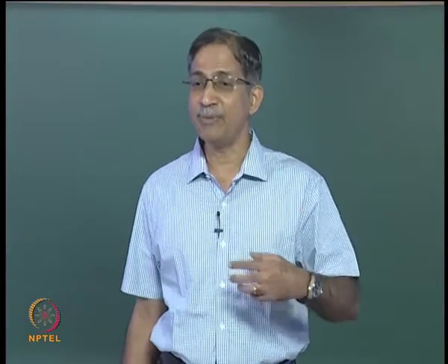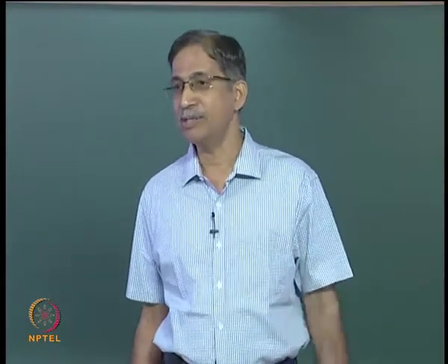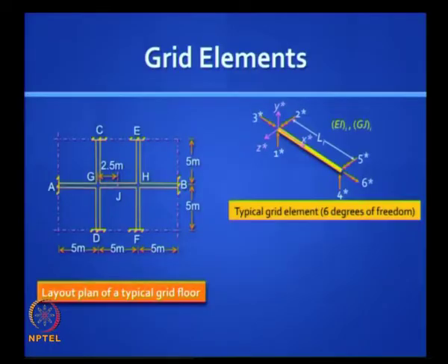If it's a space frame you have to bring in some more quantities which makes it more complex, but this is a spatial structure because the loads are acting perpendicular to the plane of the grid, and in general the axes in the global Cartesian coordinates will not be the same as the ones for the local coordinates.